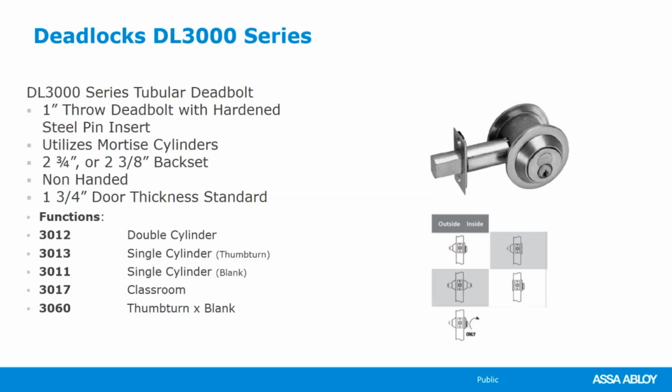You have, similar to the construction of the T-zone type lock, the 3100, a bearing assembly on the inside that works in a very, very similar way, where you have the latch bolt engaged through that assembly, and the cylinders themselves would then screw into the assembly, and they're held in place by a set screw.